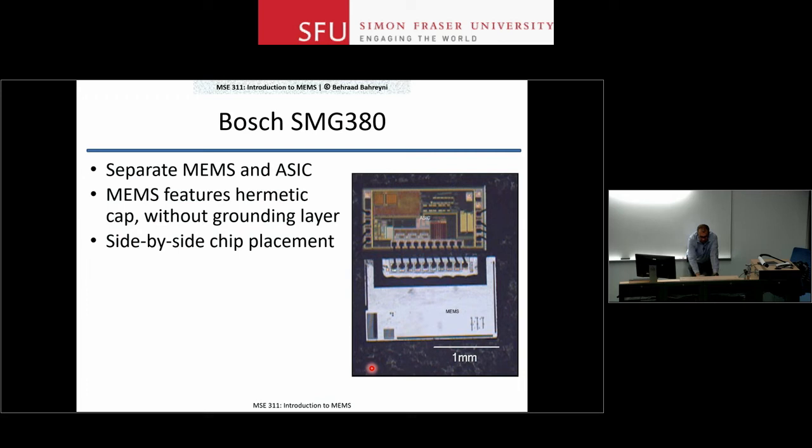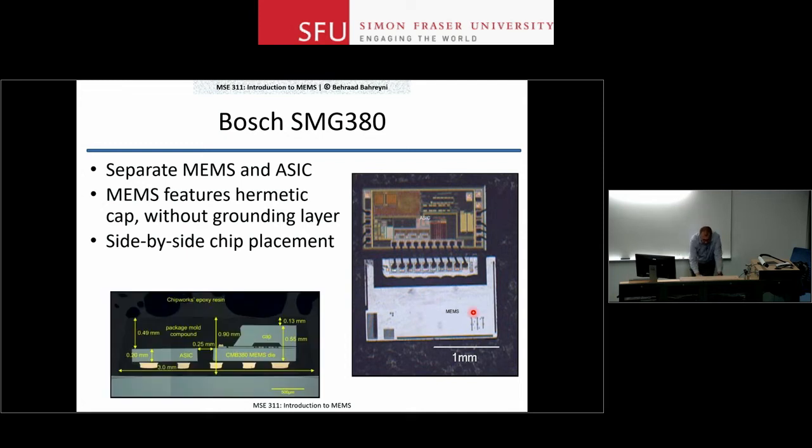So if you open it up, you see this. So this is your MEMS chip, and the MEMS chip is like this. You have your MEMS device right here that is fabricated on this bottom wafer. Then you put a cap wafer on top of it to create a small cavity here to protect your device from everything else that can happen to it. And you put this combination inside the package, bring out the contacts to the MEMS device through this cap. So these are these guys here, and then connect them to your electronic circuit, to your ASIC, application specific IC. So that's that.